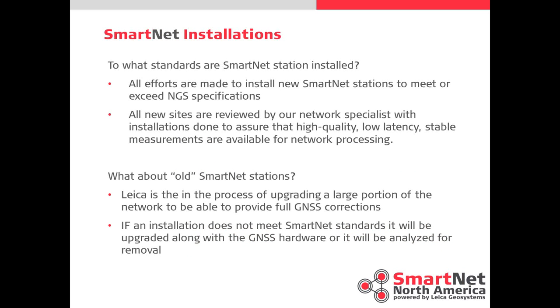A question asked on a pretty repetitive basis: how do we install our stations? We make all efforts to install new stations in SmartNet to meet or exceed NGS specs. All the new sites are reviewed by our network specialists with installations done to assure high quality, low latency, and stable measurements are available for network processing.